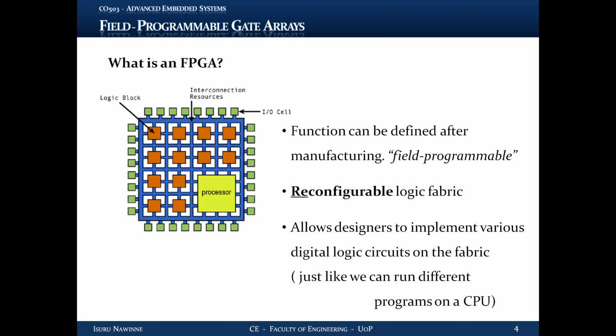If you synthesize that onto FPGA logic blocks, you can put it here. And that's the logic circuit that the FPGA will be hosting, right? So that's actually how this term field programmable comes, how the name is made. Because once you deploy a chip into the field, even after that, you can program it. You can program it in the field. That is the meaning of field programmable gate arrays.